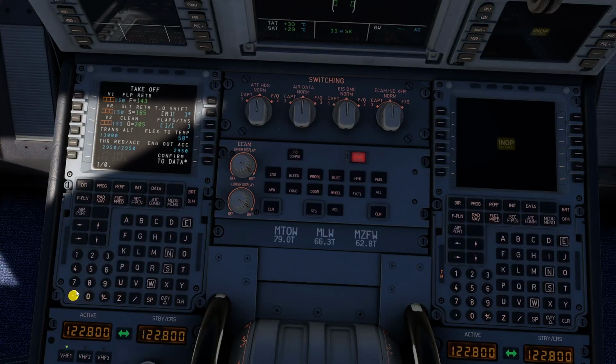So we do 0.5 up. Just exactly like that. If you're using flaps 2, put 2. If you're using flaps 3, put 3. And then put whatever the EFB tells you on this side. Okay? Click on that. Boom. Now, the reason why we push on the EFB, the send to FMGS, is because it brings this section up here, okay? So now we know, without looking back and forth, the numbers we need to put in.